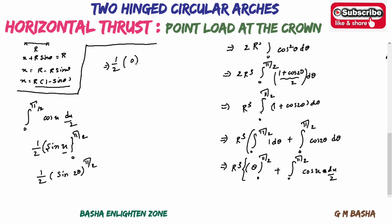So the entire trigonometric part is 0, and the remaining term is R cube theta, from 0 to pi by 2. Substituting the limits in theta, you will get pi by 2. So the overall value here is R cube pi by 2 plus 0, which equals pi R cube by 2. So this is the denominator part, that is the integral of y square ds from 0 to pi by 2, two times.